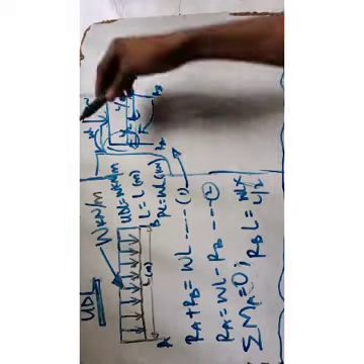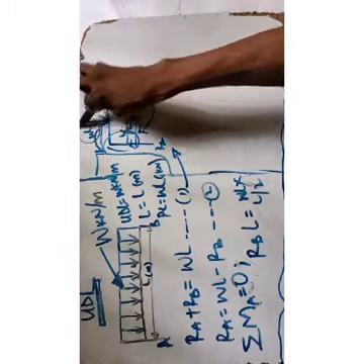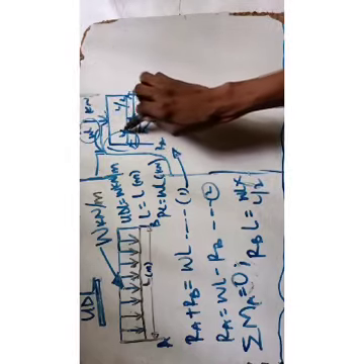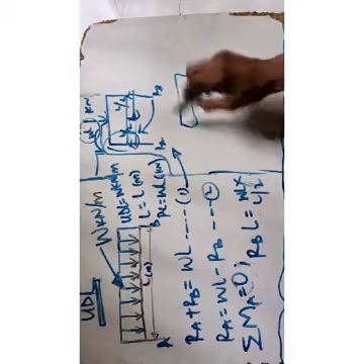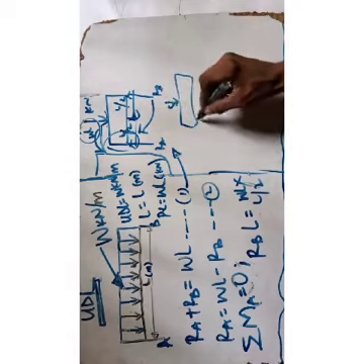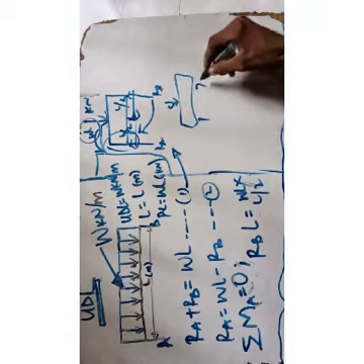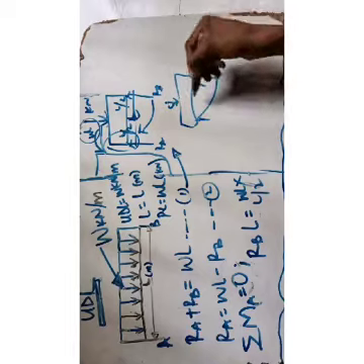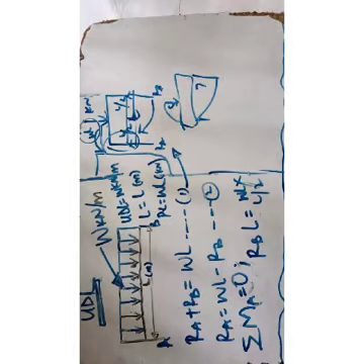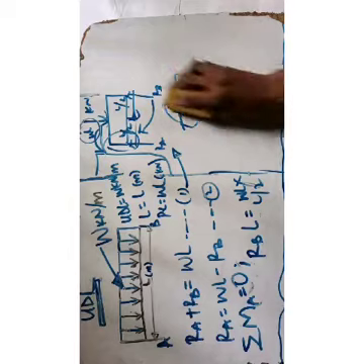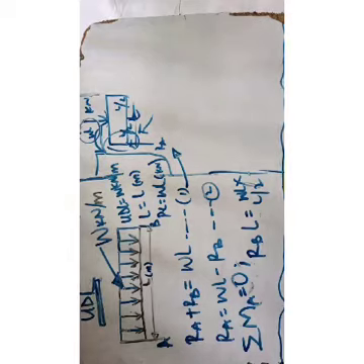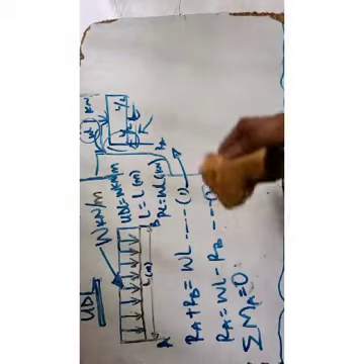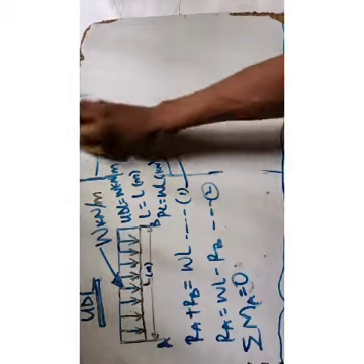clockwise equals anticlockwise, then equal to WL, the point load, times what? L over 2. Just like the way you take a normal one. Let's say this is 5, this is 7, this is 7. That will be the first here times the total, equal to this times the remaining half distance. So you're going to have something like this. Now I come again, because you need to make sure you understand this.